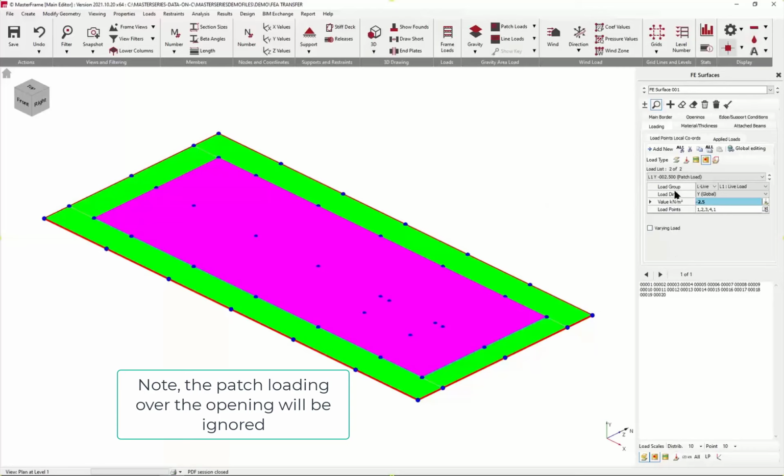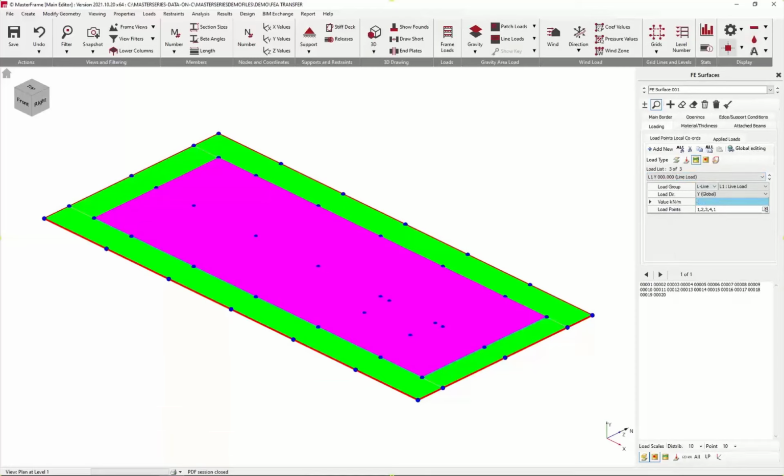The other types of loads we can handle are very straightforward, and that is, I'm just going to add this in as another load. Very simply, is a line load, and I'm going to make this line load minus 12 kilonewtons, and I'm going to put a wall around it. And in this case, I'm lucky I can just use the same node points again and make that a dead load.